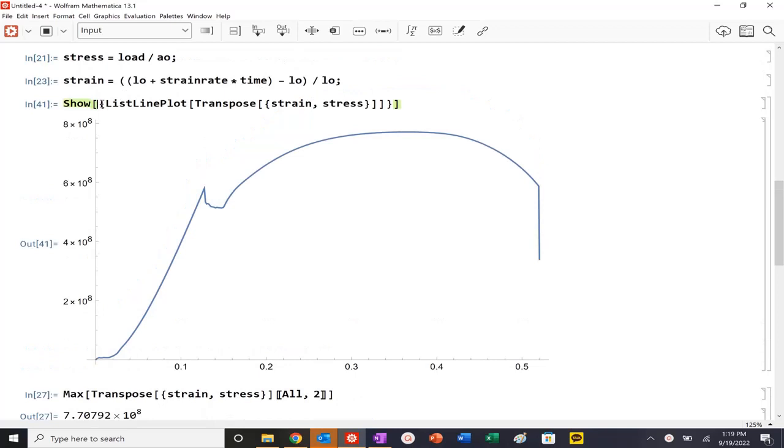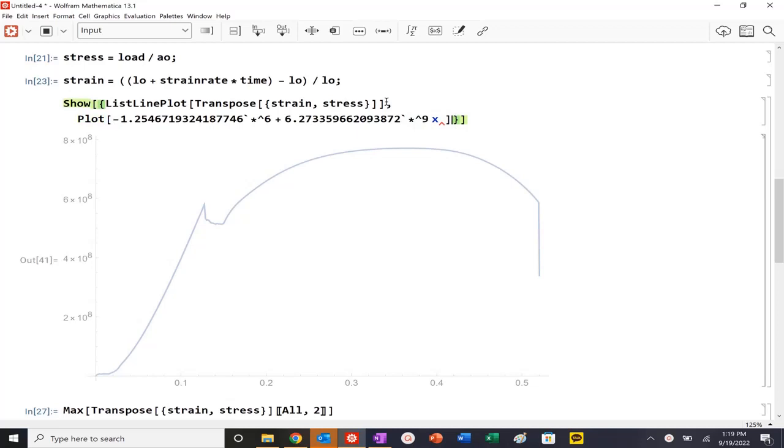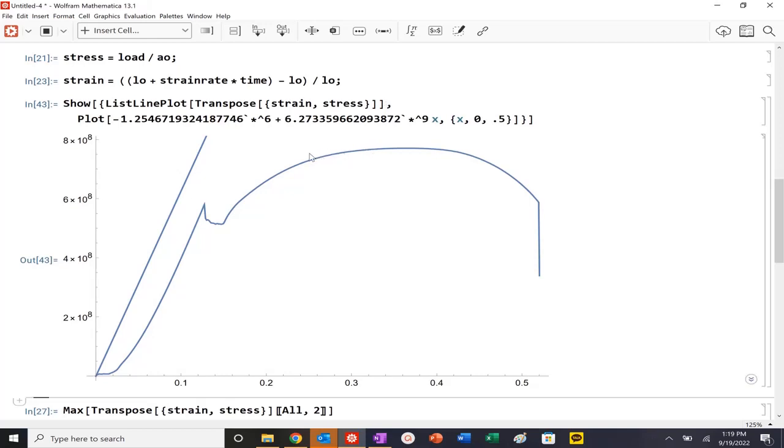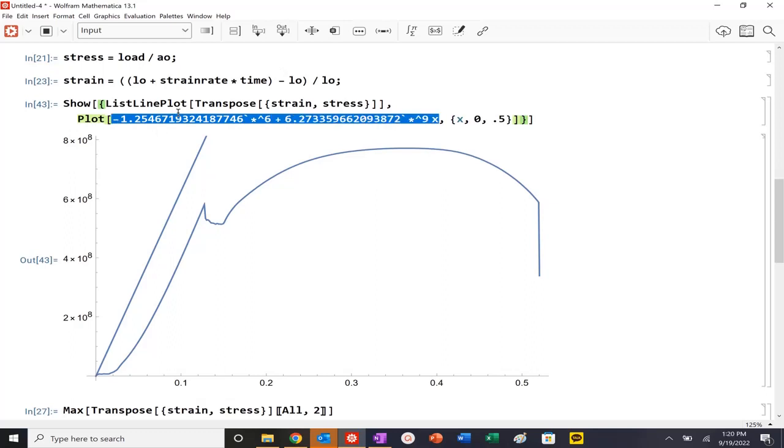And then when our extrapolated line intersects our actual line, that's where we can determine essentially the yield strength. So we could plot it here, look at it. So again, this is kind of the problem with this stress strain curve. It looks like they pulled, it wasn't completely in tension initially, because you see that kind of flat region. But again, this is the problem of loading that stress strain curve, but also that 0.002 offset, when you could clearly see linear and nonlinear regimes.